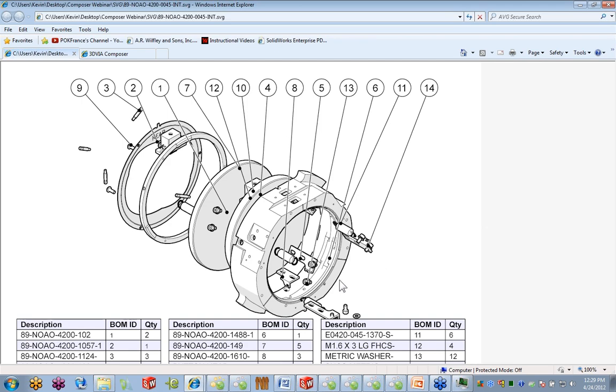But one of the things we can take directly out of SOLIDWORKS is creating these interactive vector graphics where we have a bill of material, and when we select on an item in the bill of material, it takes us to the item in the graphics area. So an interactivity with the documentation. Maybe this is on your web page. Maybe you give this to someone on the shop floor so they know all the components contained within the subassembly.